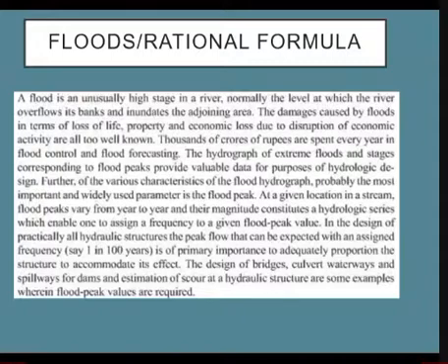In the design of practically all hydraulic structures, the peak flow that can be expected with an assigned frequency, say 1 in 100 years, is primarily important to adequately proportion the structure to accommodate its effect. The design of bridges, culverts, waterways, and spillways for dams, and estimation of scour at a hydraulic structure are some examples wherein flood peak values are required.